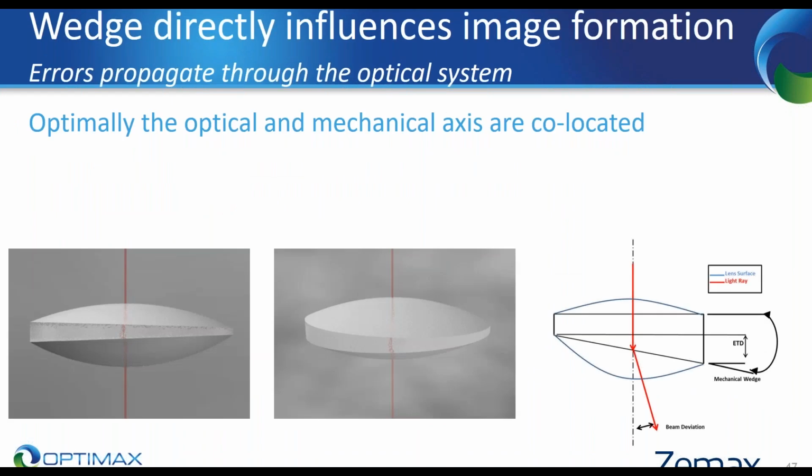Another thing to consider, and I said I'd only mention this twice very briefly, this is the second time, is that mid-spatial frequency errors should be considered for sub-aperture polished surfaces. Surface irregularity is typically measured interferometrically or with a profilometer. Again, for spherical surfaces, usually this is interferometrically, and your specification must contain a value: band-limited RMS, robust peak to valley or PVR, or peak to valley over the clear aperture.